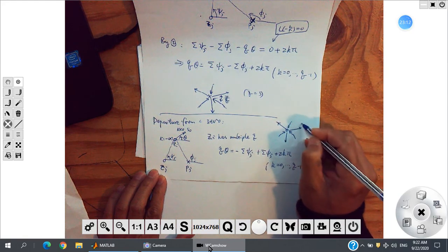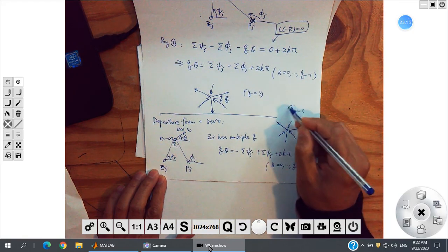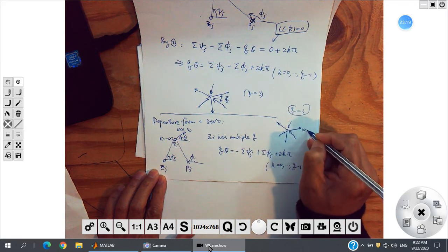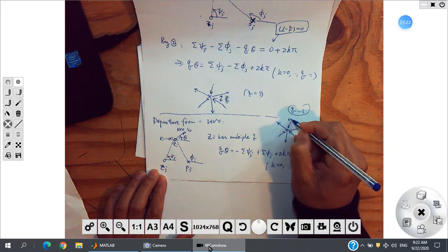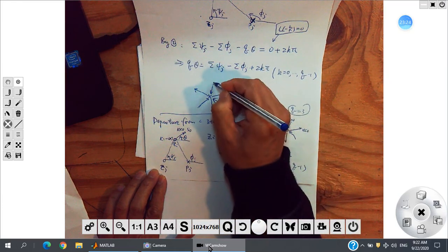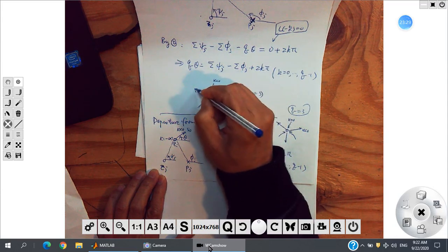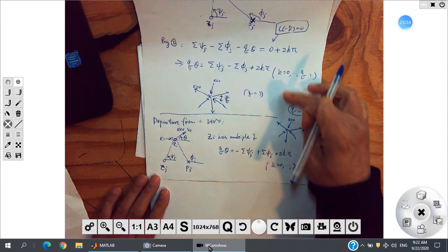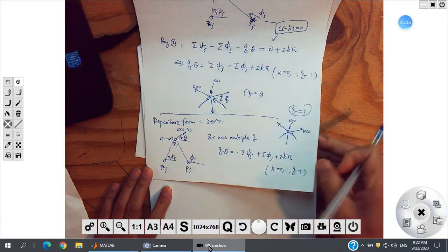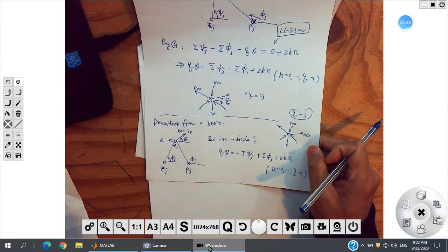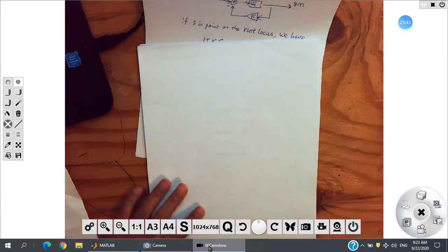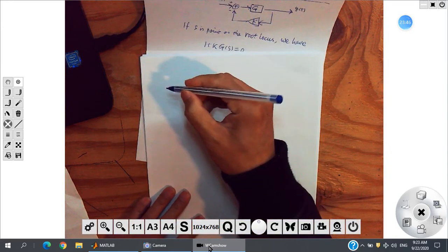If q is 3. Departure, that means k is negative, and arrival is k positive, right? And this one is arrival, k is negative, and departure, that means k is positive, right? Things like that. Okay, so these are the poles and zeros where the locus leaves or arrives, and we can calculate the direction. We can use an example to see what happens.